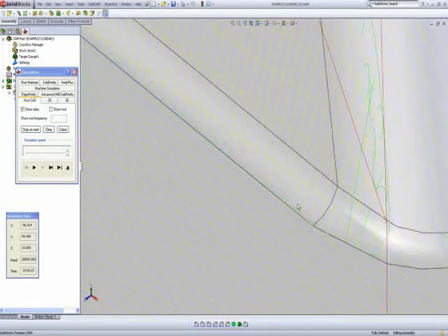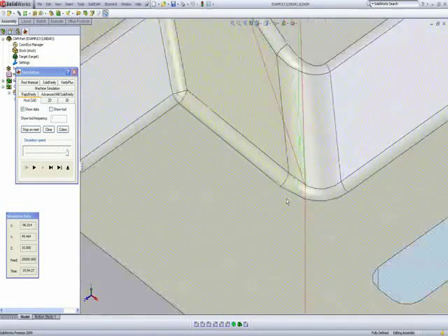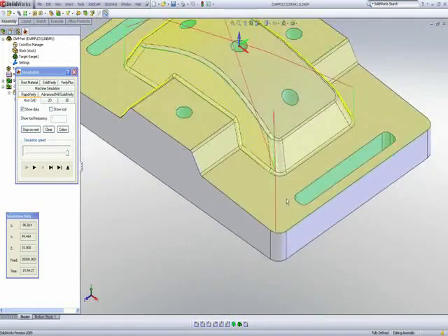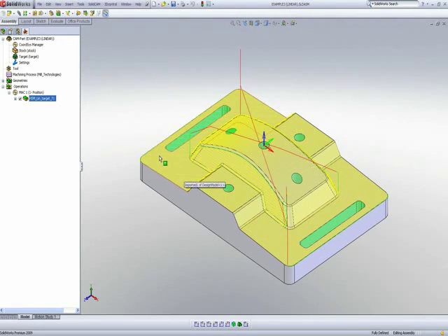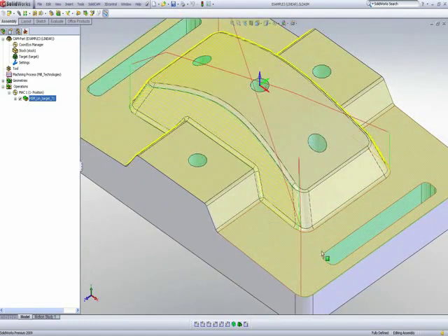You can also see that this area here is curved according to the radius that I added as my fillet area. We've finished the entire part within one operation using linear operation, and every single area has been machined correctly. What we still have to do, however, is finish the corners here, the radiuses themselves.